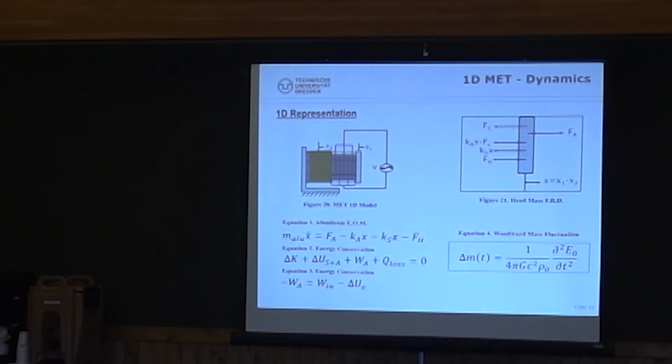so this gets cancelled out. And the other components of the force that I have are then the elastic force, the potential spring force of everything that's connected to the screws, the brass, the aluminum, and the spring force of the actuator itself. I also have a hysteresis force, which is basically a damping force, which arises in piezoelectric material due to the internal friction that's in the piezo material itself. So you have rotation of the domains, and then also viscous friction inside.